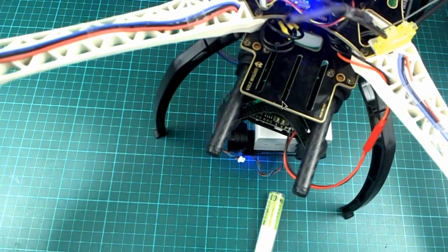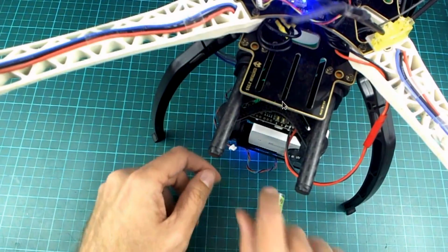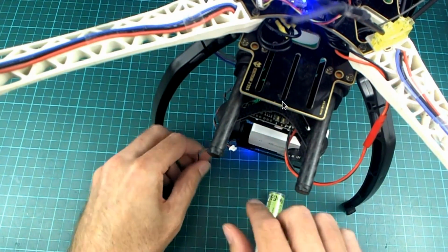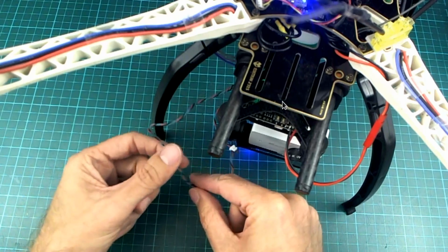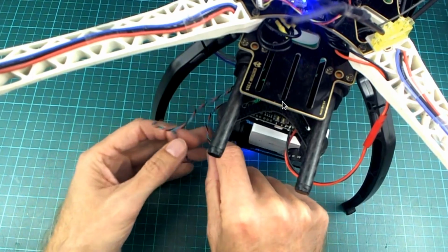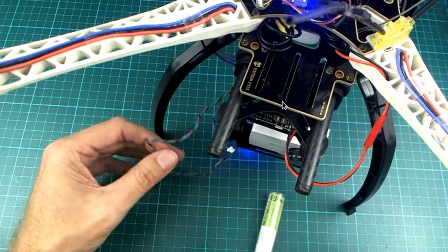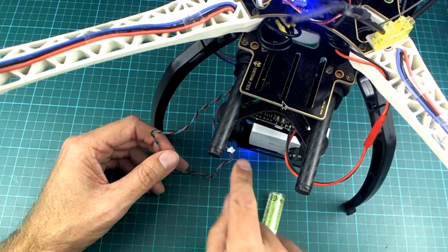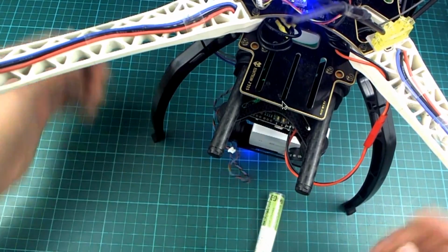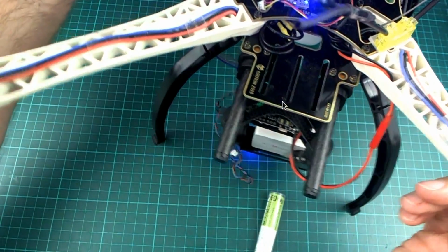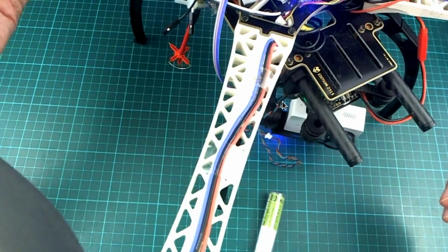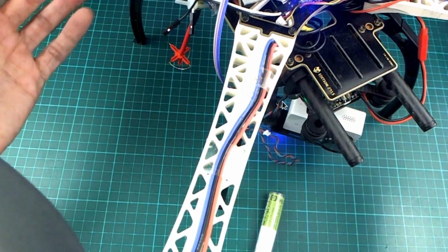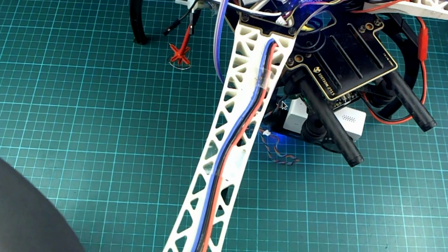Anyway, so it's probably enough about that. You'll notice one thing down here that we'll see in the video as well. I had a problem with this gimbal in that all of a sudden it was working fine. I used it for a few flights, and then all of a sudden I found that when it got to 45 degrees or so over in this direction, so when it turned itself to about there, it would just lock itself rigid and stop working. And it turned out to be I2C errors.